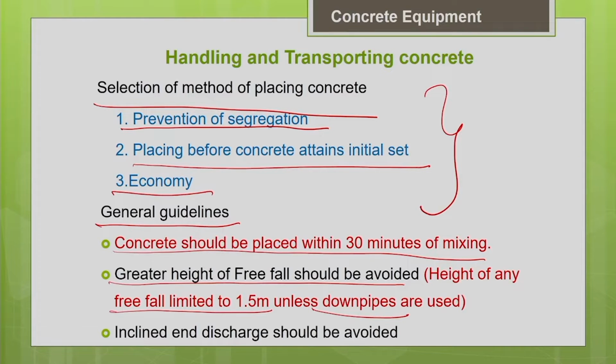But for free height of fall, the maximum height allowed is only 1.5 meters. Beyond that there are more chances for segregation. And another important thing you should note is that inclined end discharge should be avoided.